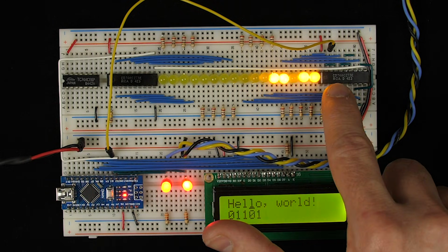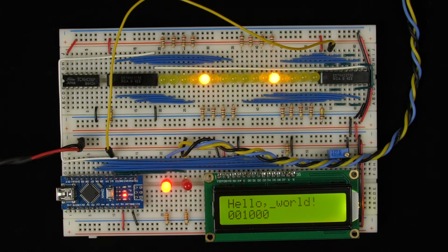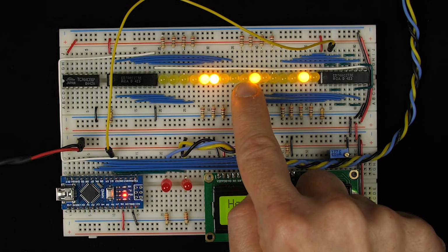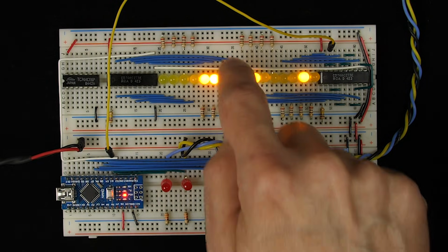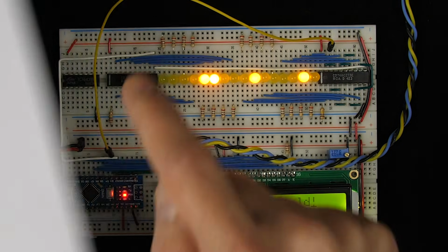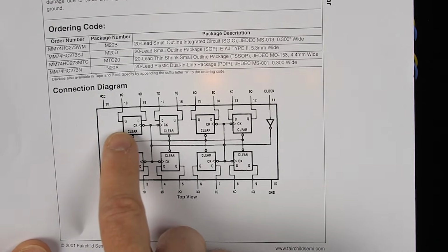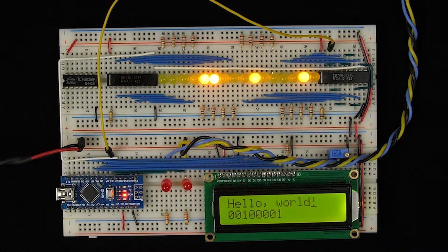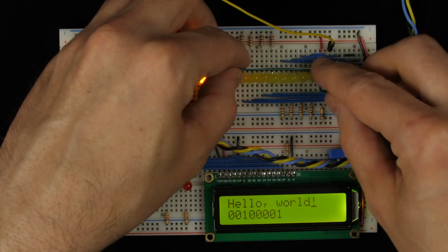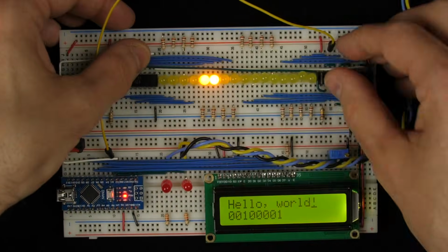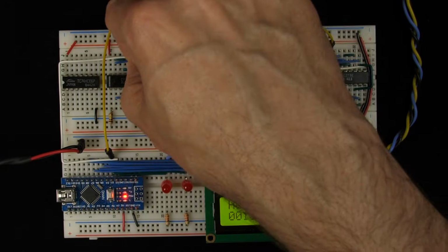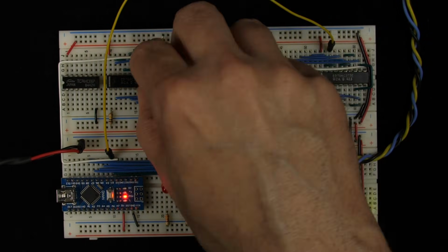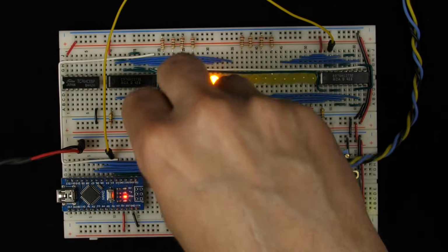So now I just need to connect into the second 8 over here. So I need to take the output of this LED and get it into the input for that one. The output of that one is going to be pin 2 here. And then the input of the one next to it, that's this LED, comes all the way over here. So that's the top left again. That's going to be pin 18. So pin 2 down here goes up to pin 18. And so now I'm basically going to do the same thing on this chip that I did over here, which is just wire all of the outputs of each flip-flop to the input of the next one.